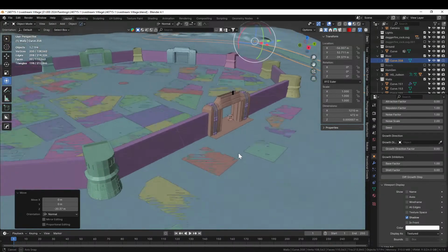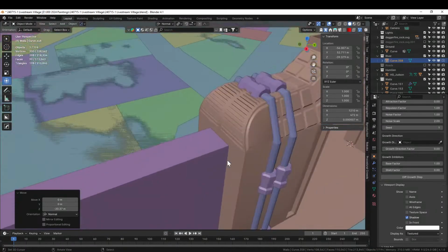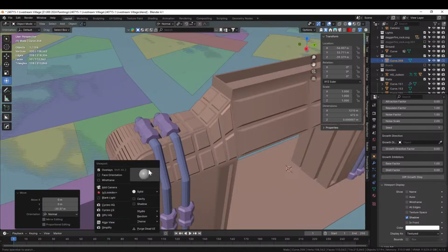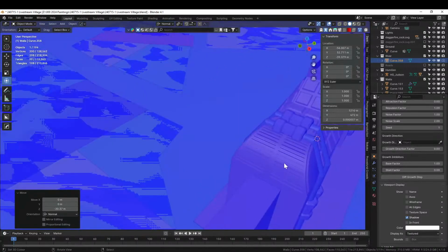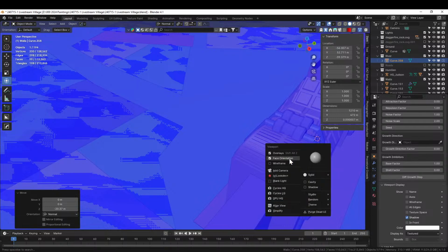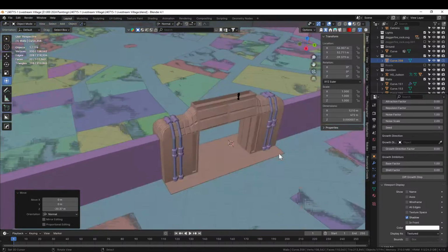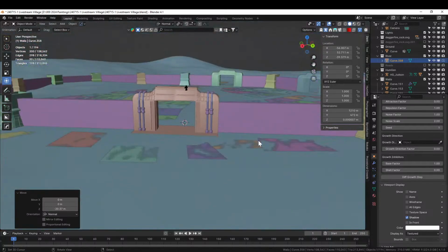Well, the why is a couple of reasons. I can give you that. So first off, it could 3D print weird if it was inside out. It also reverses what the normal maps do. So if something is pointed inward, it would point outward if it was reversed like that, because basically it flips the normals if the geometry is bad there. So because it's not, the normals will all point outward instead of jumping around. In some things it matters more or less than others, but say you were using normal maps to do things like belt buckles and stuff, so they weren't even really in the geometry.